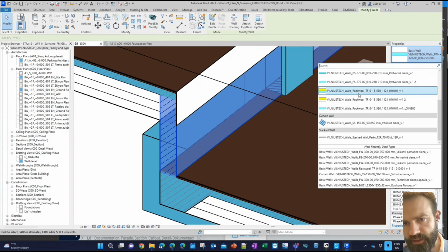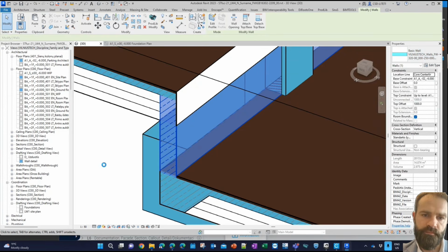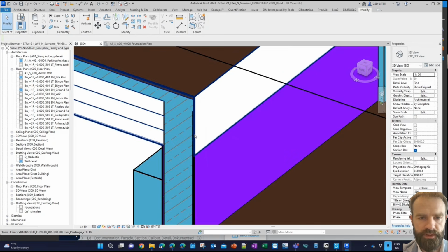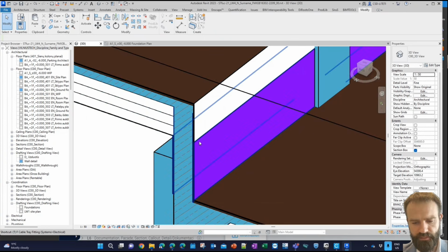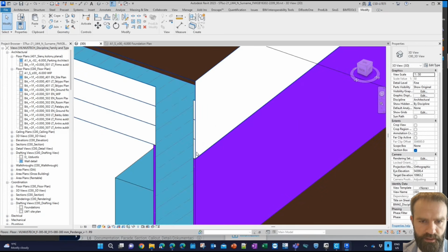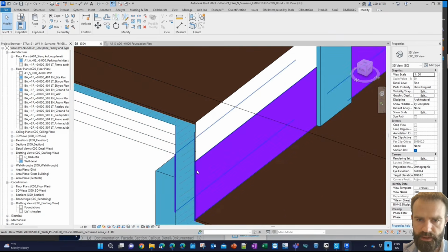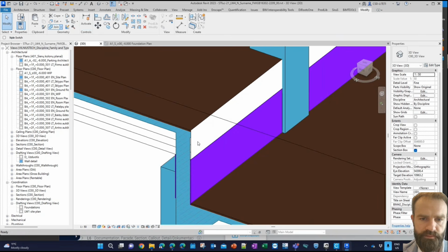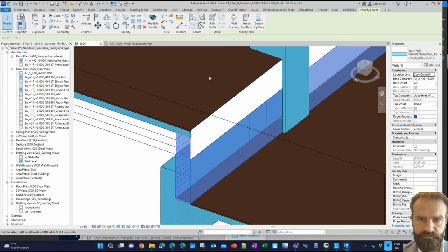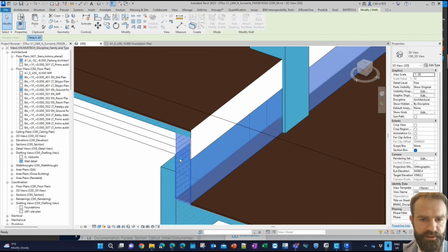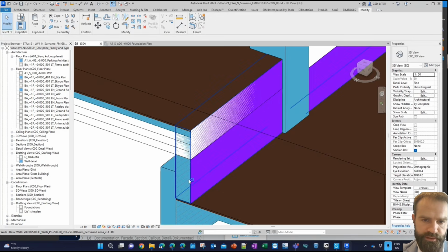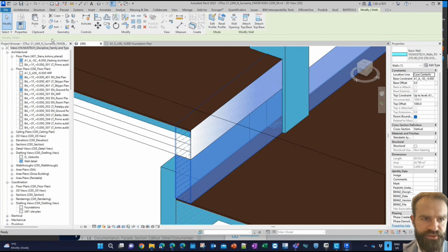And also I can use a wall with plastering. So if I select a wall with plaster, plastering will close this part, the white part, and all the finished parts will be nicely joined. Okay, so it should be joined, but I don't see it. It's not joining. If I select switch join order, in this case, maybe I need to use detach and just attach base.